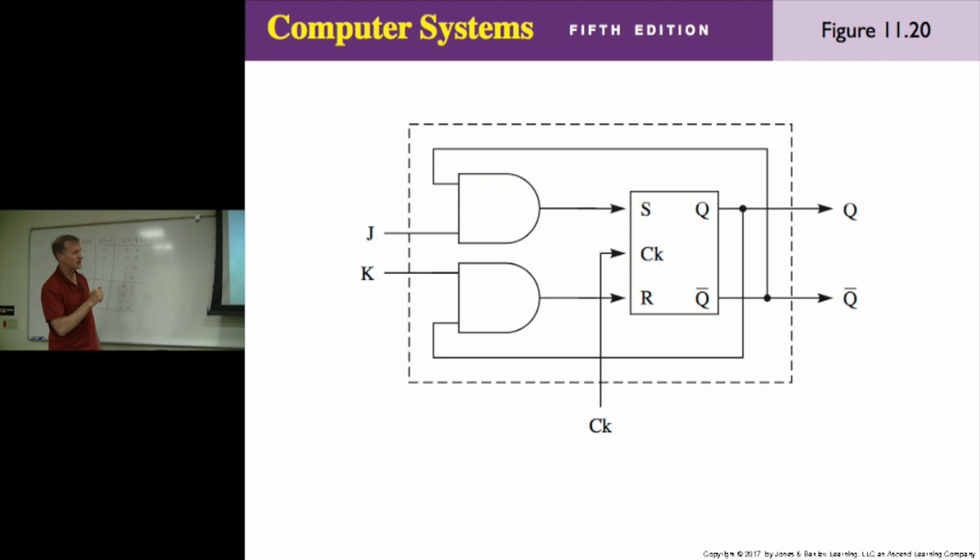It'll be 0, 1. And what is the 0, 1 condition? It's the reset. So after one clock pulse, it'll be reset. On the other hand, if Q is 0, then it'll be 1, 0, which is the set. And so it'll set. So again, it will toggle. See how slick that was? You can maybe figure that out in some sort of ad hoc way, but this is a systematic way to do it.